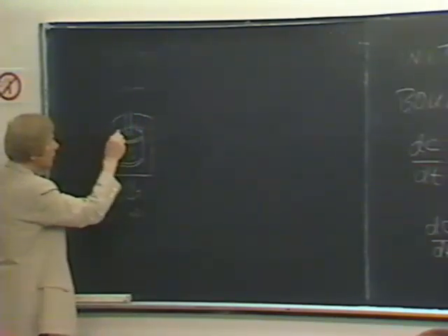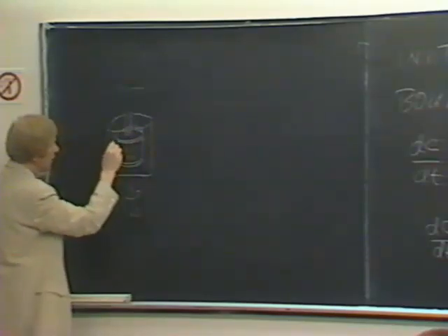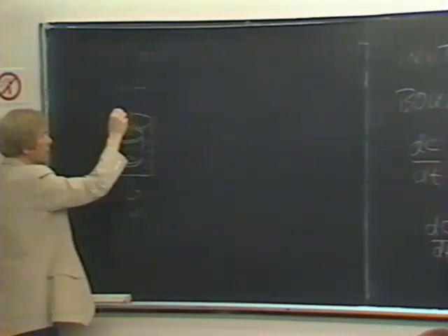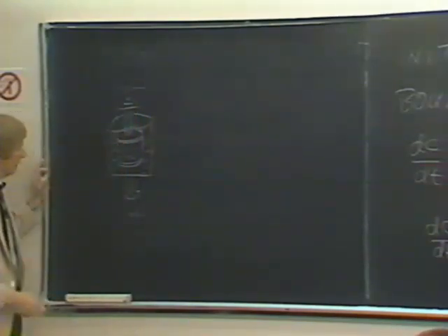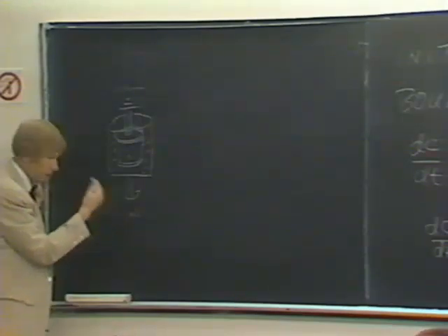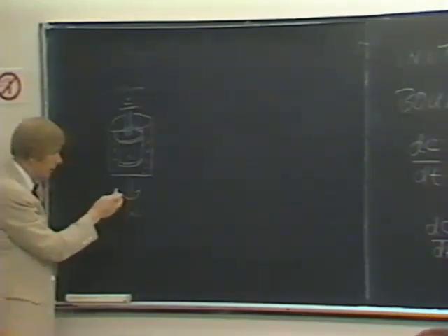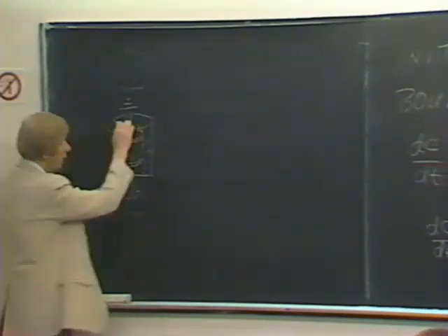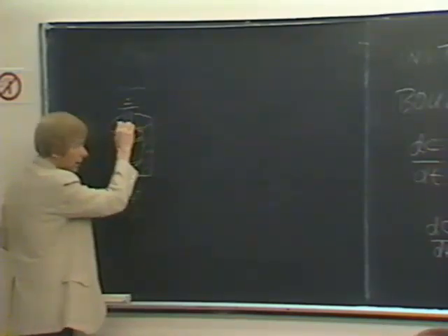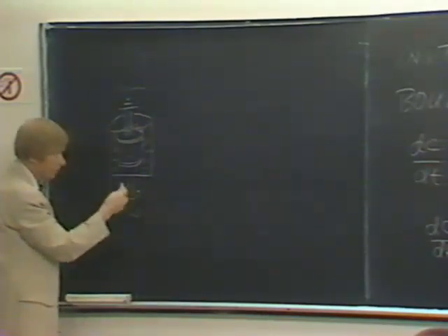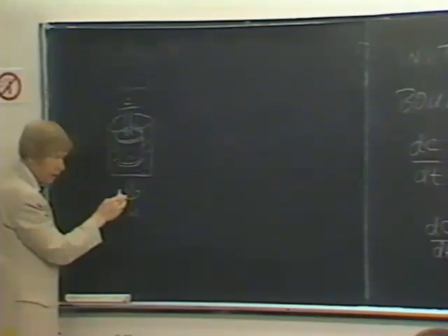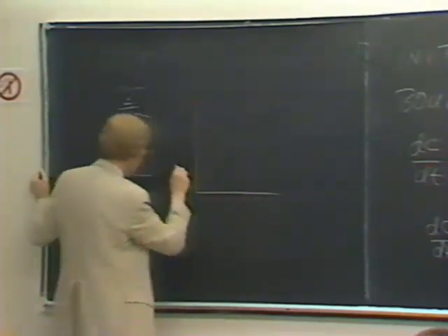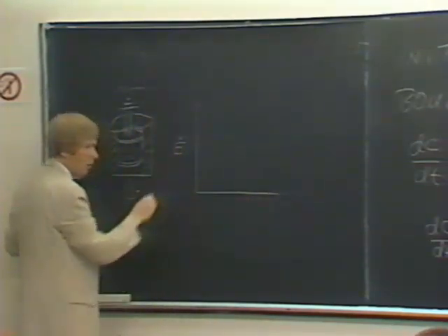Here, and fill this space in here with water. Then this is mounted on, let's say, some kind of a mount. Then the technique is to rotate this outer cylinder at a given speed for, say, 1 minute, and then lift this out and weigh it, and then put it back in and rotate this again for a minute, and do that repeatedly until you can plot the loss in weight. I'll call it E dot, loss in weight per meter of surface, as a function of